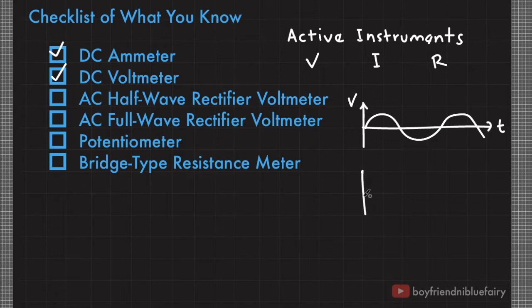However, when your input involves alternating current, it is easier to measure the voltage if you truncate the part of the current that flows in the reverse direction. In other words, we just use the positive valued voltage and assume that through these values, we can represent the overall voltage of an AC signal by calculating, for example, the peak voltage or the root mean squared voltage, etc.